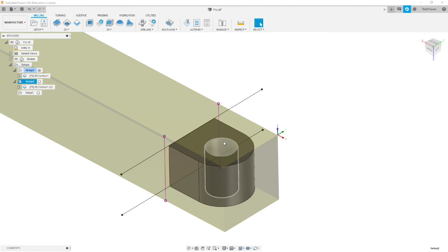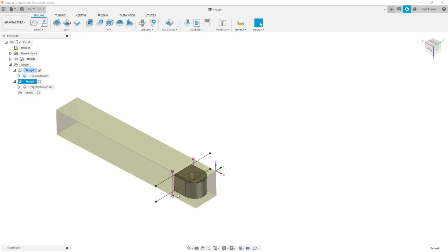We're going to machine this hole, and then we're going to machine around the outside perimeter of the part, leaving the material that's connecting it to the stock. The reason we want to do that is we want to cut all the way around this profile and cut all the way through, so there's not much deburring. But when we cut this backside edge, we want to leave a little bit of material on a part this small. It'll allow us to leave some flash there, and we'll break it off by hand and do some hand filing.